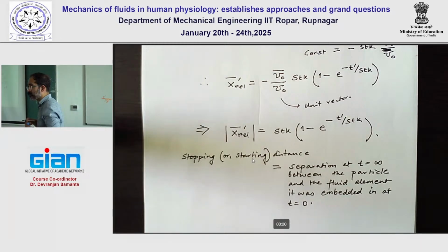Earlier we mentioned in the Stokes definition also that we have the Cunningham correction factor, which captures the effect of lambda. So that is still valid for this also. Now when we say the particle velocity with respect to the fluid, we are talking about with respect to the molecules of the fluid. Okay, that's a good question, because the mean free path is a material property.